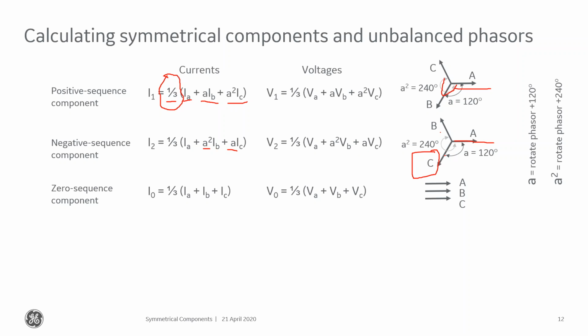By 240. So that's going to put B right here. Now, if I take this C and I superimpose it on A, right? And I superimpose B on that. That means my negative sequence components are going to be 0 if I have a truly symmetrical power system, right?